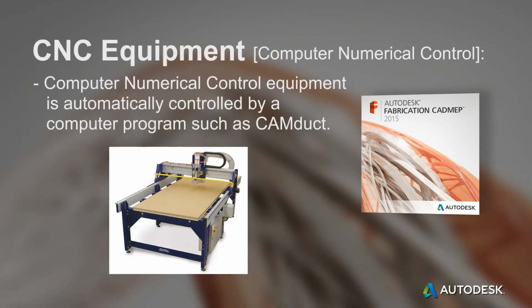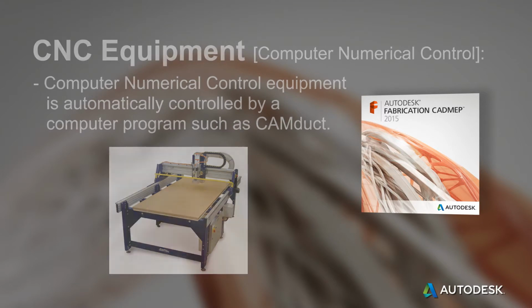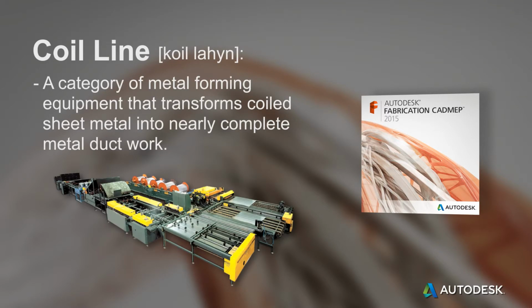CNC equipment. Computer numerical control equipment is automatically controlled by a computer program such as CADmep. Coil line, a category of metal forming equipment that transforms coiled sheet metal into nearly complete metal ductwork. The most sophisticated models uncoil the sheet metal, cut to size, notch and punch, apply insulation, and bend to shape. Coil lines only fabricate straight shapes using the full width of the sheet. Smaller parts and bends are cut on plasma tables.